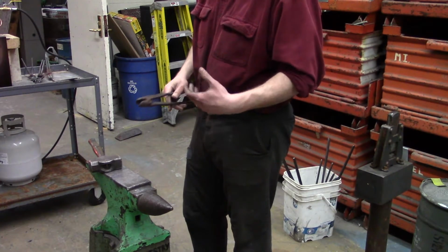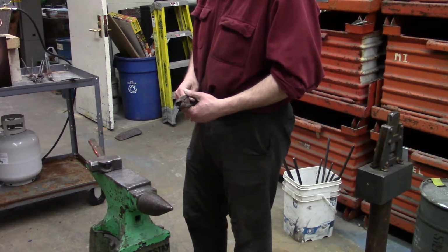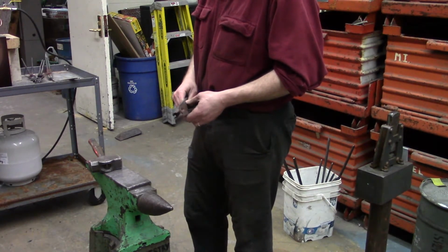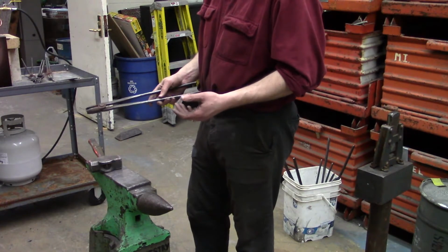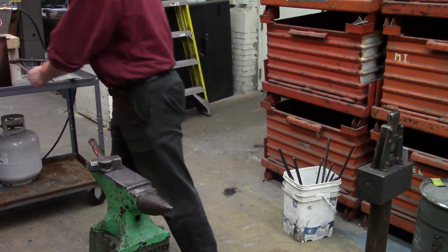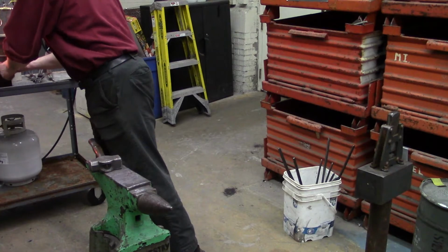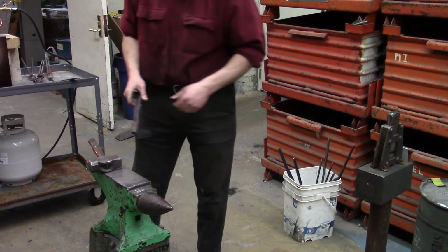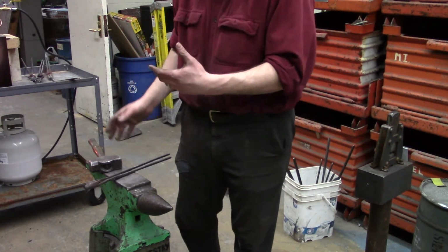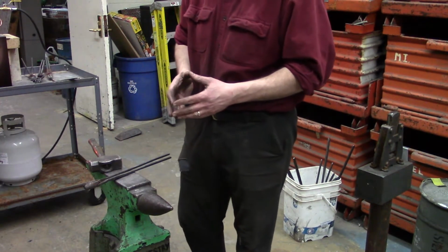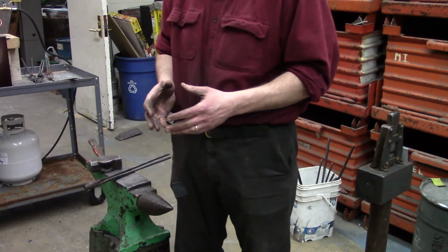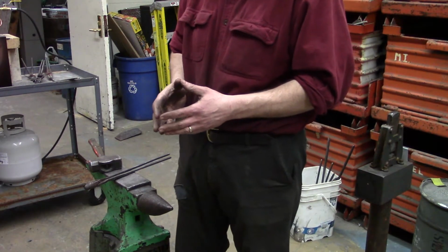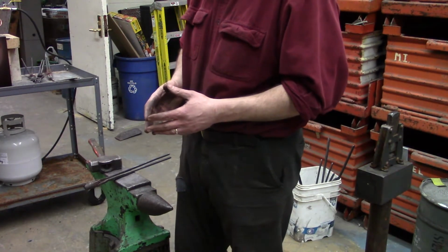A ladder pattern Damascus dagger from some steel that we welded and forged earlier in the evening. This is Material Science 401 lab class. The materials in the dagger, in the blade here, are some industrial bandsaw blades and some nickel shim stock. The bandsaw blade seems to have a composition somewhat similar to S7 tool steel.